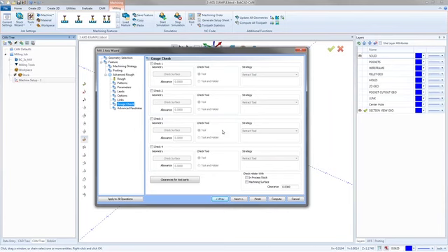But you got to think a gouge can happen from so many things. It could be bad step overs, too large of step overs. It could be bad boundaries. It could be so many things that factor in. There's so many ways to take care of a gouge that sometimes gouge checking is the last one that I even go through. Not to say it's not one of the most useful functions when you do need it, because it is one of the best functions when you need it. But I'd say for the average 3-axis guy, probably not going to do too much gouge checking. Now, if you start getting into doing parts with a lot of fixtures and stuff,